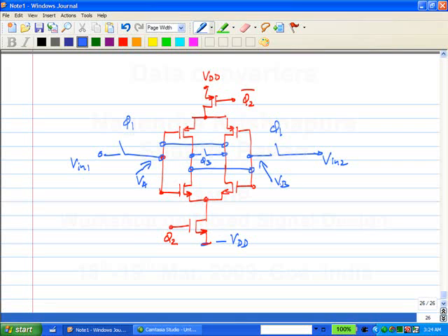Of course, one thing now left over is, we know that we operate mostly with single supplies, right? So if you have a positive supply and a negative supply, and you want to make the circuit operate with a single supply, it's very easy. Just add VDD to every node voltage, correct? So in other words, this will become 0, and this will become 2 VDD. But you can always call 2 VDD as VDD, right? So this becomes the supply. You understand?